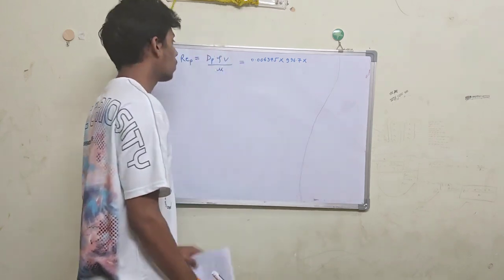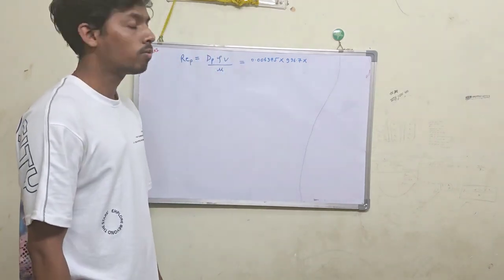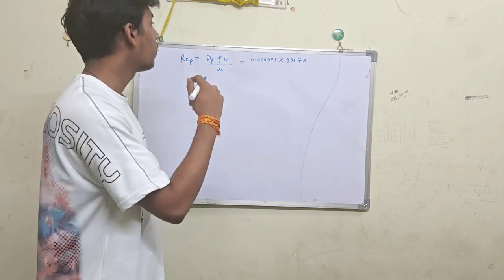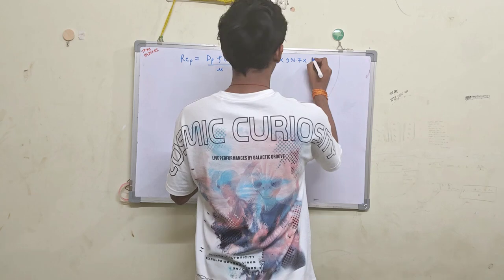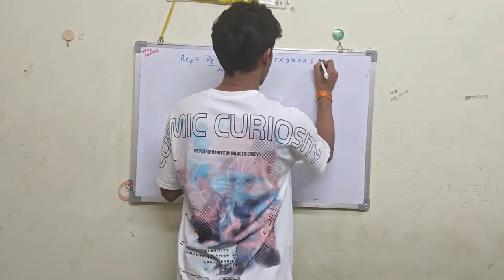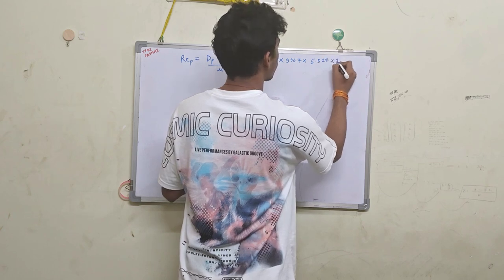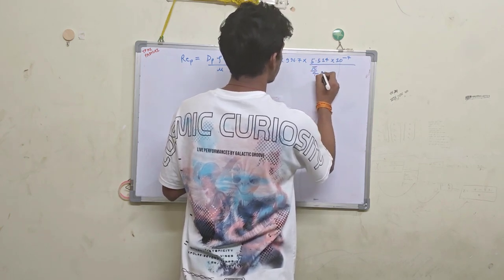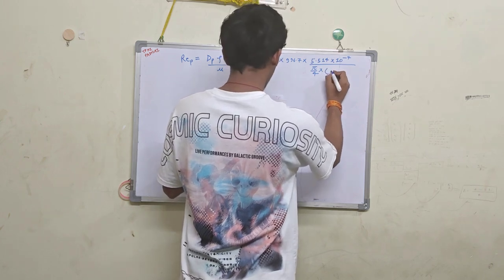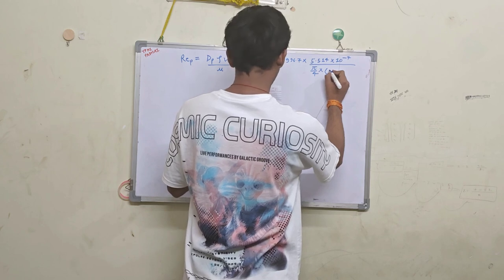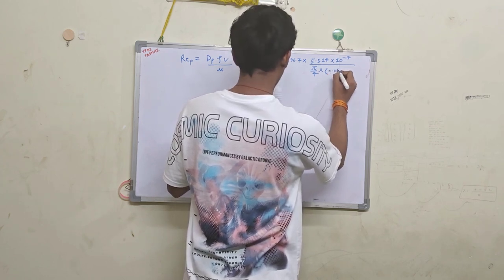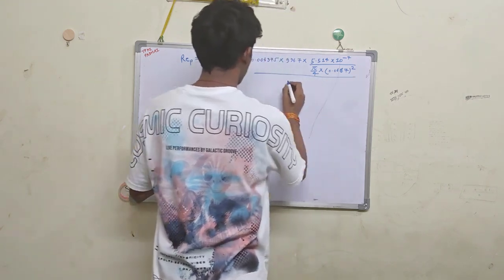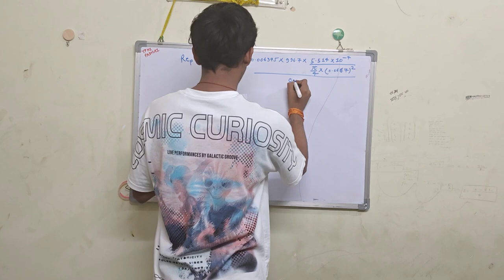and now the velocity is not given. Instead, the volumetric flow rate is given. So we can divide the volumetric flow rate by the cross-sectional area of the packed bed, and then we'll get the velocity of the water. The volumetric flow rate was given as 5.514 × 10^-7, divided by the cross-sectional area, where the diameter is that of the tube or our packed column, 0.0667 squared, and divided by the viscosity given at 26.1 degrees Celsius.